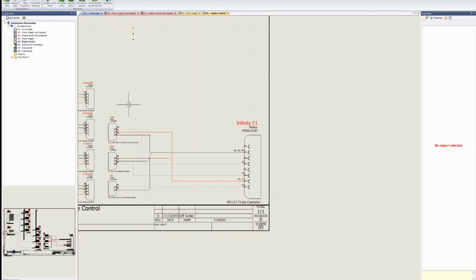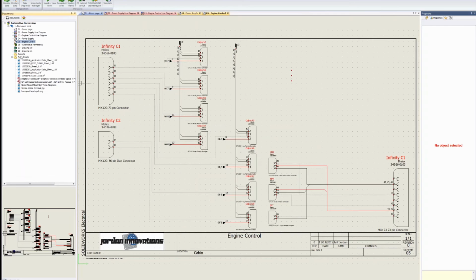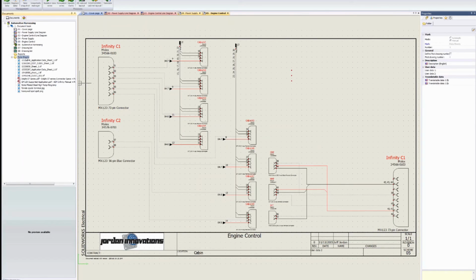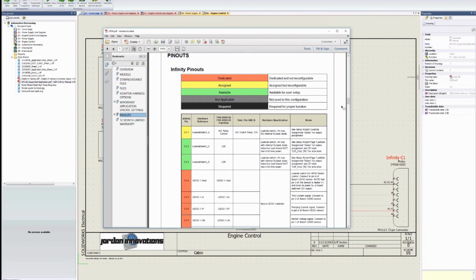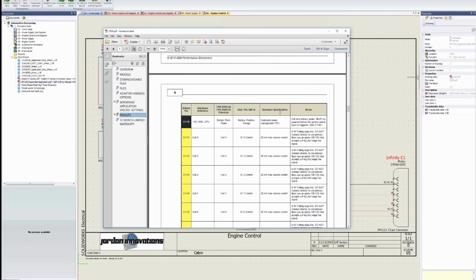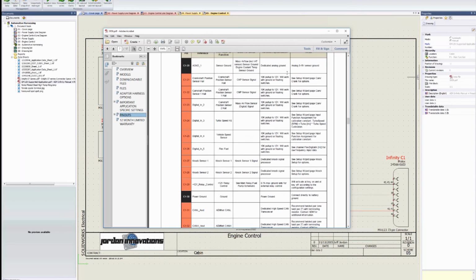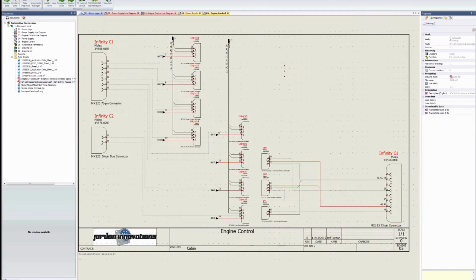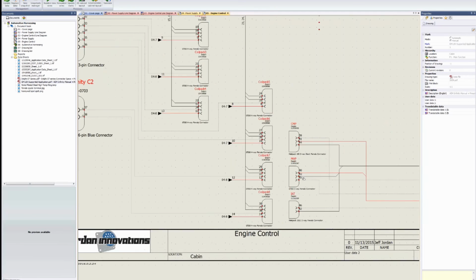And how do you know which pins are which when you're in the document? You've got to be jumping in and out of data sheets. Well, over here on the left, I created a folder within this project that has my data sheets. So I can open this. This is the manufacturer's PDF for this engine control unit for this application, and I actually helped develop this. We have all of the information, so I can be just inside the project, 2 seconds into a PDF, checking pins. Okay, got the pins I want. Let's put that connector down. Let's connect our sensors. Again, everything's numbered automatically.